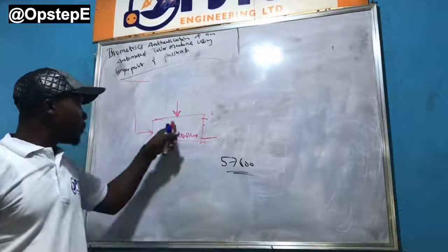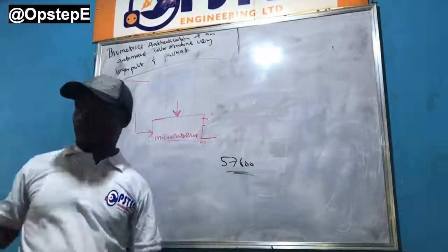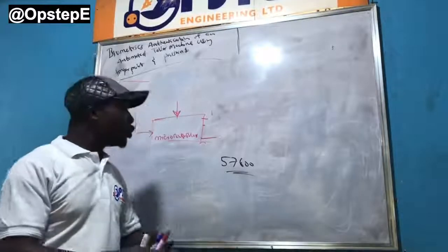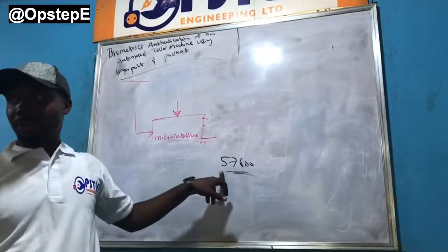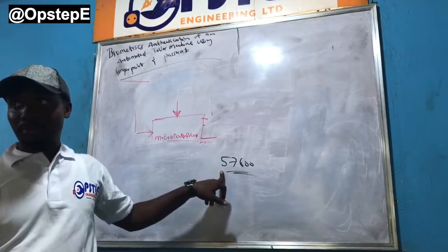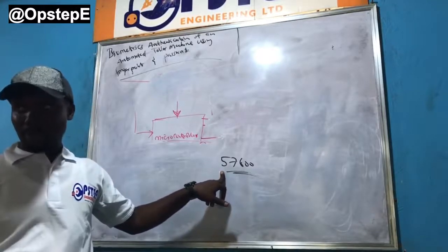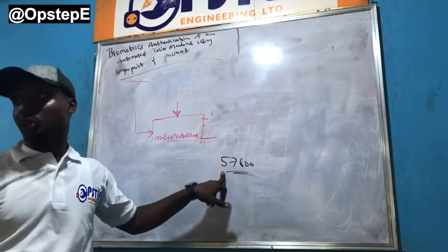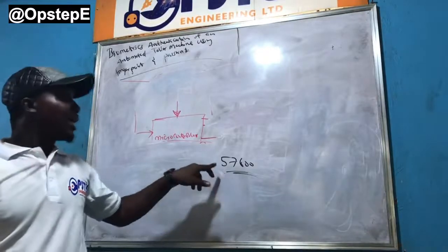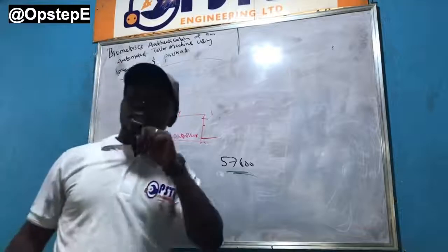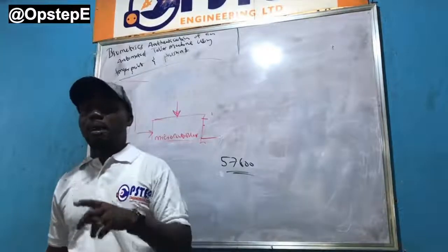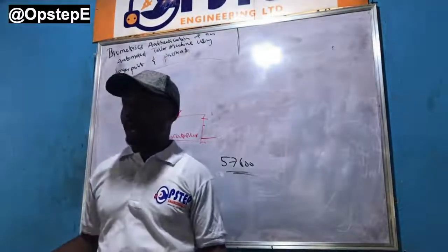Now, if you pick up a 16F877A that you guys use, it will not be able to stand this baud rate at 4 MHz. But maybe it might be able to stand it at 20 MHz. Maybe. I think you should be able to start at 20 megahertz. Now, if you start at 20 megahertz, the possible problem you might have might be program and memory size issue.